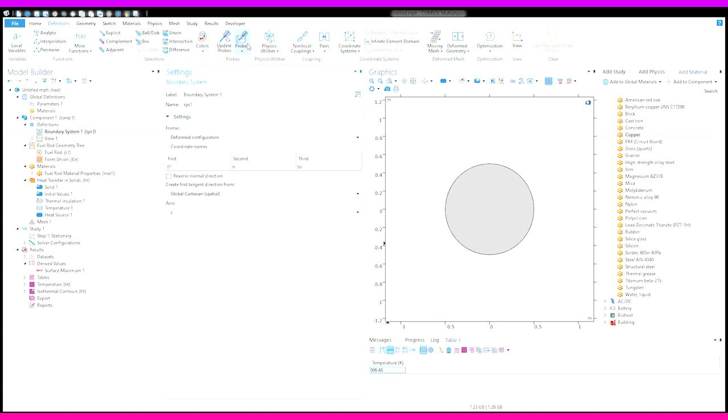First, for a parametric study, we need a way to measure the response of our variables to the parameter being altered. In the definitions tab, one of the most useful things is probes, because they allow us to do that. A domain probe will consider information in the entire shape. Boundary probes will consider obviously the boundaries. And a point probe behaves just like a real-world thermocouple. In essence, they're all just measurement devices, and they mimic the things you might use in your